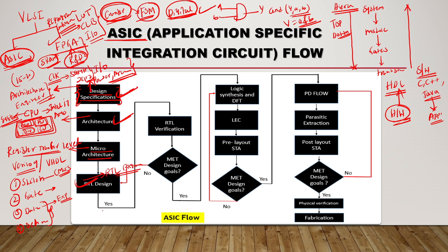And next, it will go to the RTL verification. Okay. So by using Verilog, up to something like FIFO or FIFO RAM, single port RAM, we can write the Verilog code and we can verify by using a test bench. But if you go for complex designs like SOC or system on chip or IP, you can't use this Verilog. You need to go for SystemVerilog and UVM. That will be done in the RTL verification.